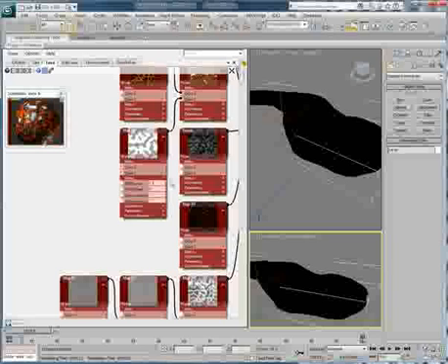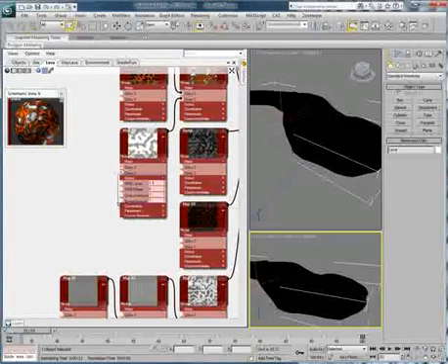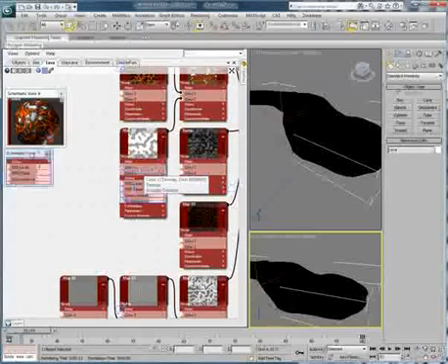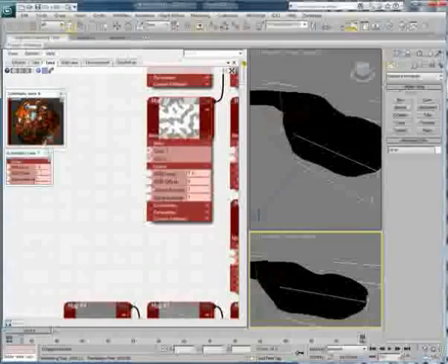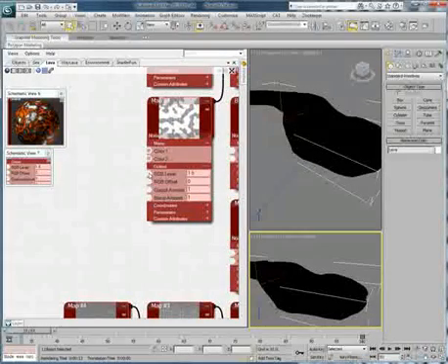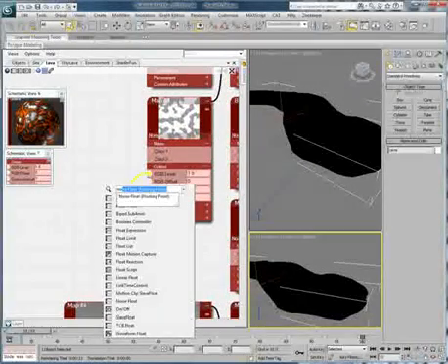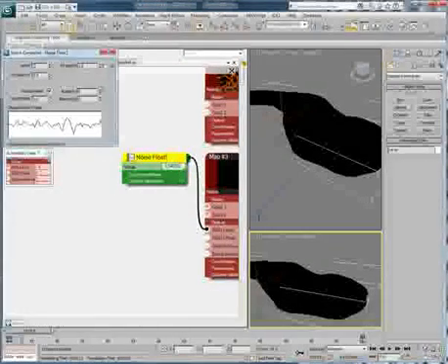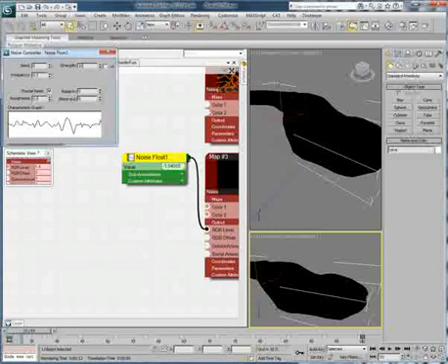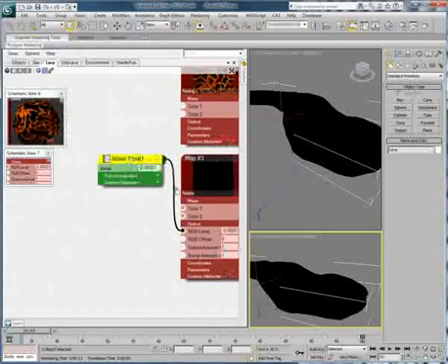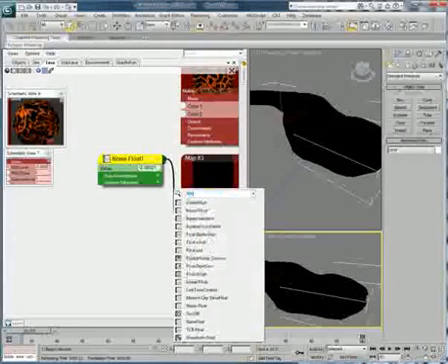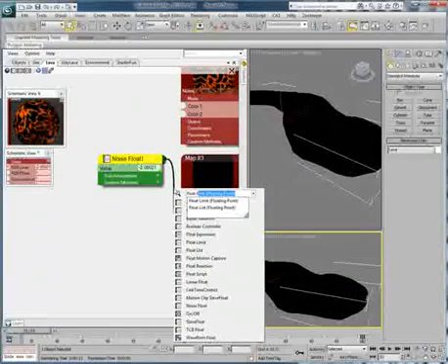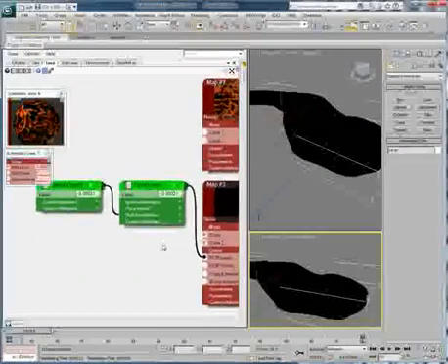And I can make it of just different values. So if I go in here and I say, hey, I know that I'm going to want to be able to see what this RGB output is at different places, I can do that. So I'm just going to go into this RGB output and I'm going to add some controllers to it. So I'm just going to drag out a noise controller. So here's my noise float, and I'm going to double click to go in here, and I'm going to set the strength to 10. And then what I'm going to do is actually insert a limit controller. So I'll type in float limit, and that'll bring that there.